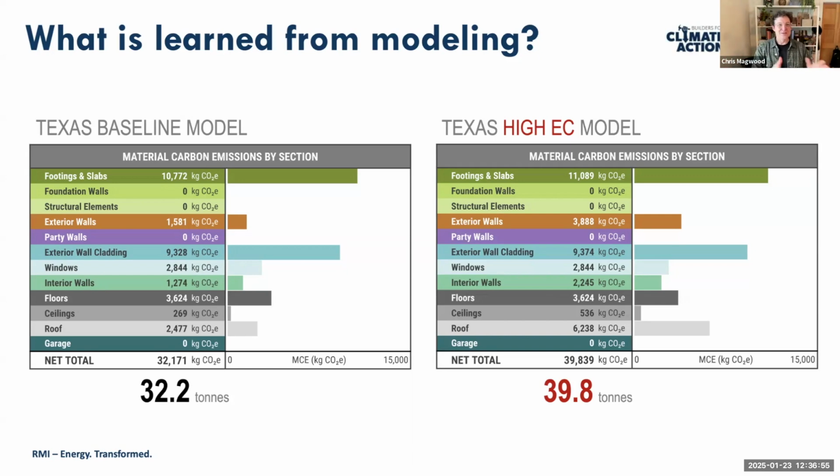You give the tool the area, and it does the takeoff for you. Sometimes it asks you, is this on 16-inch center or 24-inch center, to refine that. But by and large, the tool is doing the material takeoff based on area.